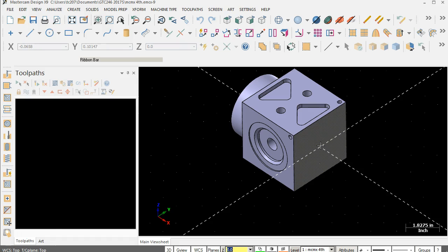We're talking about probing though as well, because I need to have the tool length offsets be able to adjust, because as soon as this is no longer a square and it goes to a rectangular part, sure, I can spin the rectangular part, but I've got to be able to raise up and lower down based on those orientations. So I really want to probe this and, back to that previous conversation, have the tool length offsets independent of this part. A dedicated location, a tool probe, and the spindle probe to define these geometries.